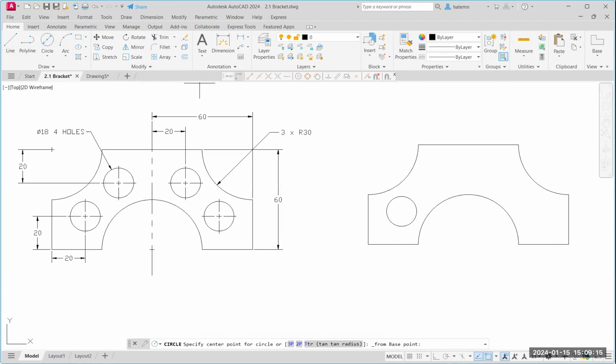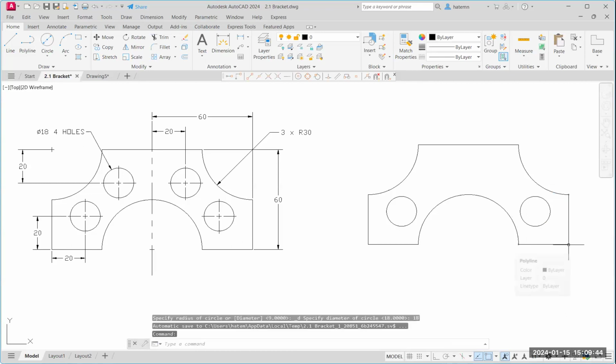So I'm going to select this, and I'm going to go ahead and do my at symbol. And now since I'm moving to the left, that's along the negative side of my x-axis. So I'm going to put my -20, comma, I'm still moving up, which is in the positive direction on my y-axis. Because remember, you have to pretend that this is your y, this is your x, and this is your 0, 0 right here. So I'm going to type in my 20, hit enter, and then type in my diameter.